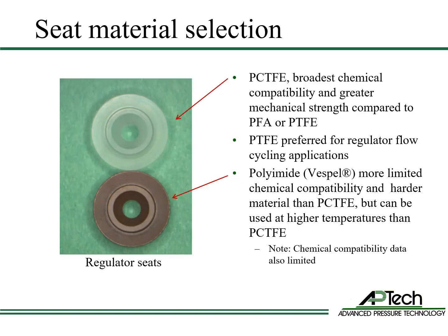When selecting seat material for valves and regulators, ensuring chemical compatibility is very important. PCTFE offers the best combination of broad chemical compatibility and mechanical strength compared to PFA or PTFE. PTFE is preferred for regulator flow cycling applications where the seat has potential for abrasion-related seat wear.